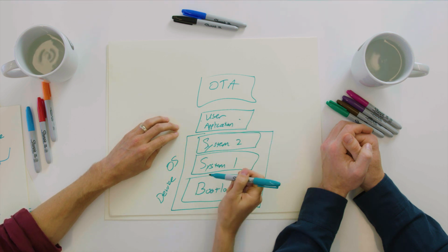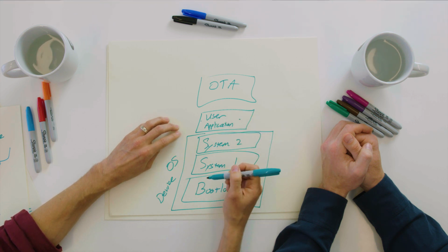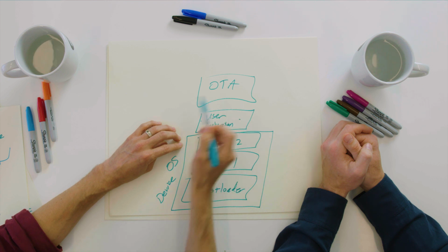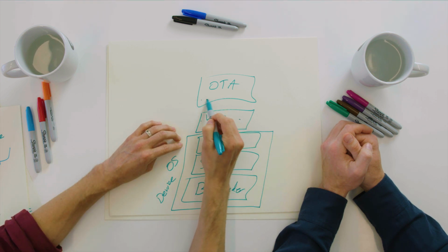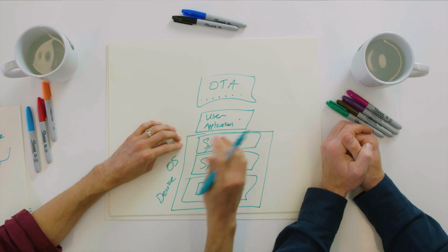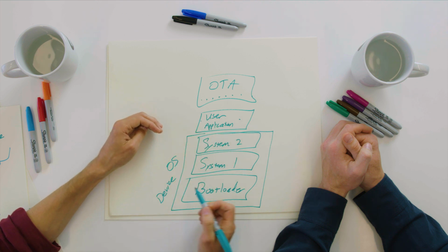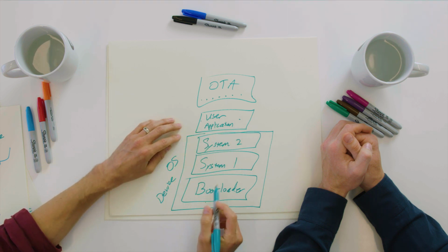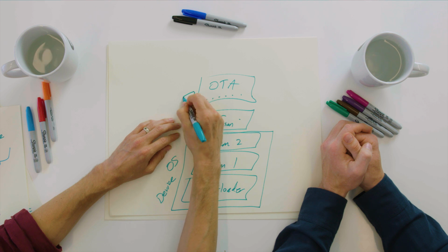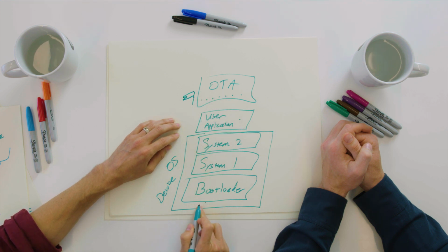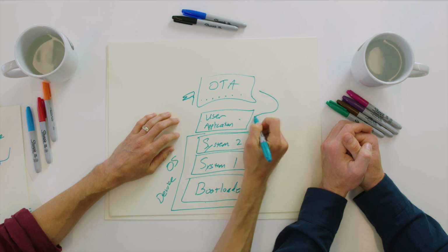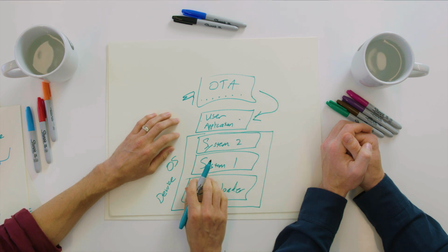your context switching back and forth between running the user application and then taking care of system tasks. Running the user application, taking care of system tasks. One of these is saving all those chunks from the OTA into this spot. When it's all done, we say, bye-bye, signal, we're shutting down, and the whole thing reboots. When the bootloader sees that there is a flag set that, hey, we have an update saved, it will, again, verify some checksums, and then copy this into that space.